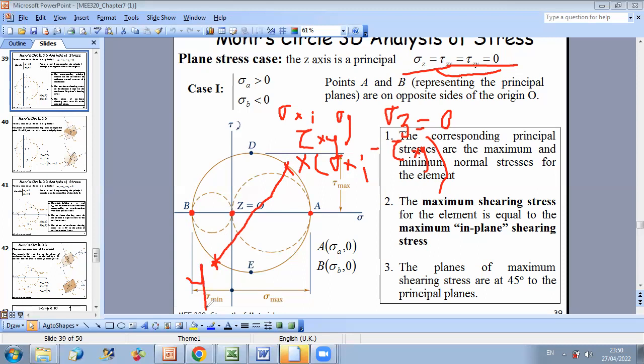So on the Mohr circle, I should rotate an angle of 180 degrees from x. If I take the origin of the circle C, the angle from Cx to Cy is 180. So once I put points x and y, the coordinates of point y are sigma y, plus tau xy.